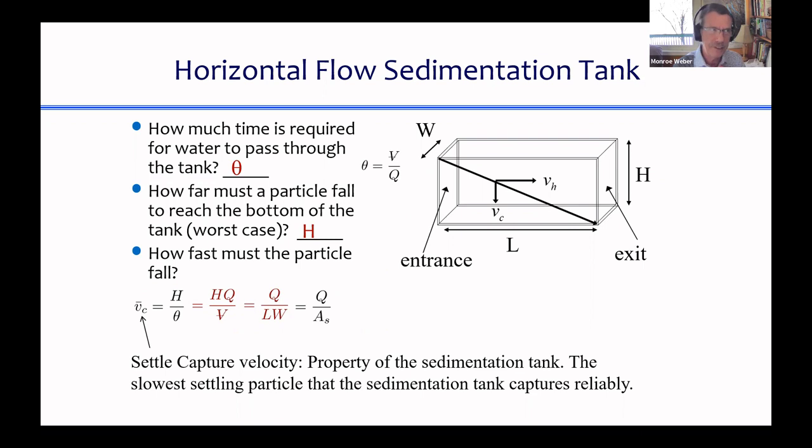If you were measuring turbidity at the effluent of this tank, what do you think would happen as it slowly fills up with sediment? Or we have mass conservation, so we know that the particles are going to go somewhere, but there's no more room in the tank. So your logic that they probably end up in the effluent is good, but then it's fun to go down the path of, well, why? What actually makes it so the particles get transported to the effluent?